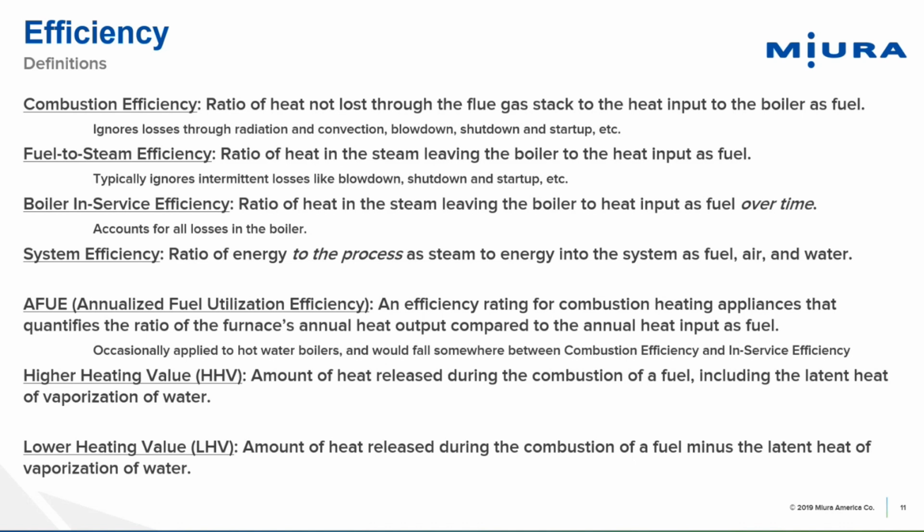And then system efficiency is the ratio of energy out of the process as energy as steam to the energy coming into the system as fuel, air, and water. And so that's really what the user is going to care about: how much heat am I getting to my process to make whatever my product is.